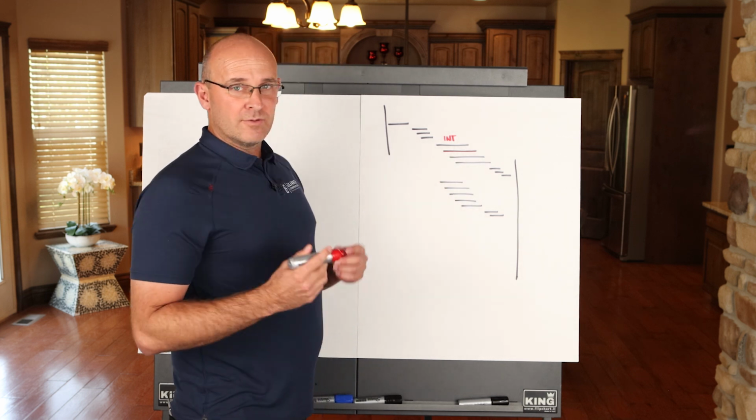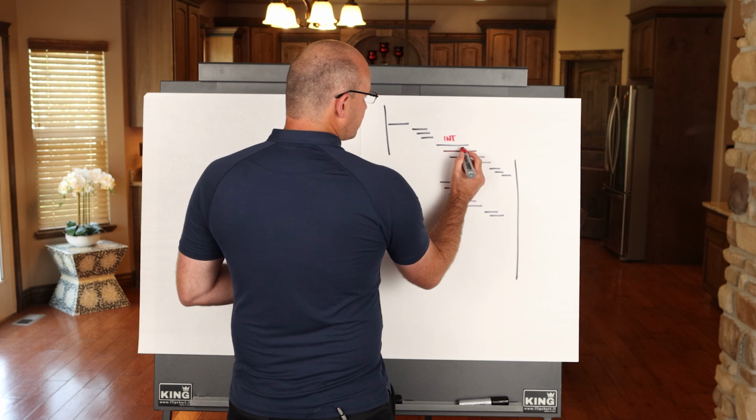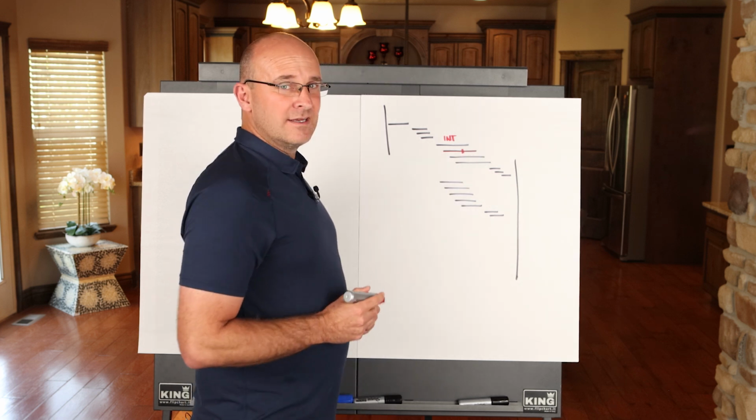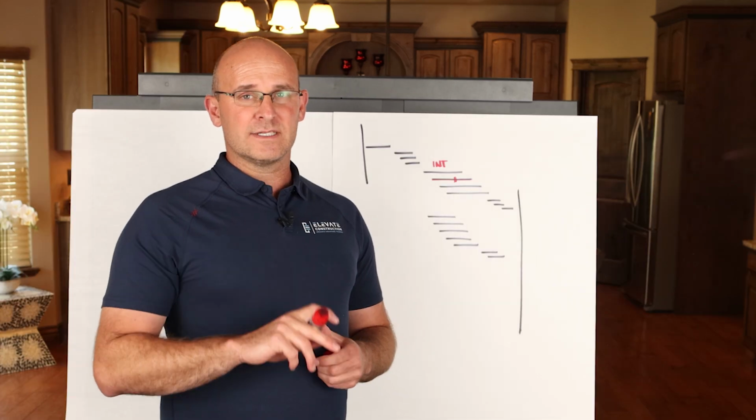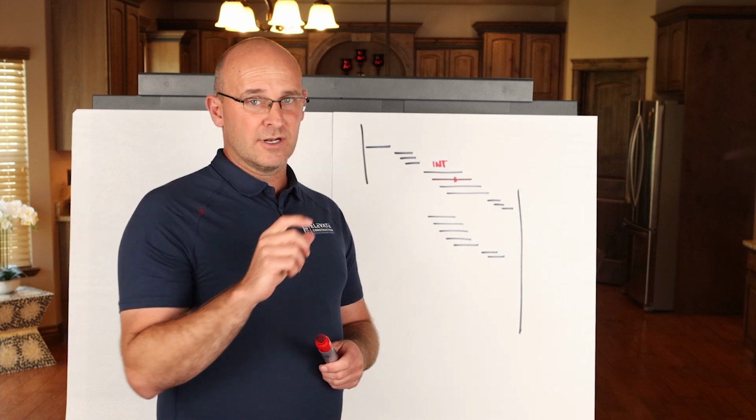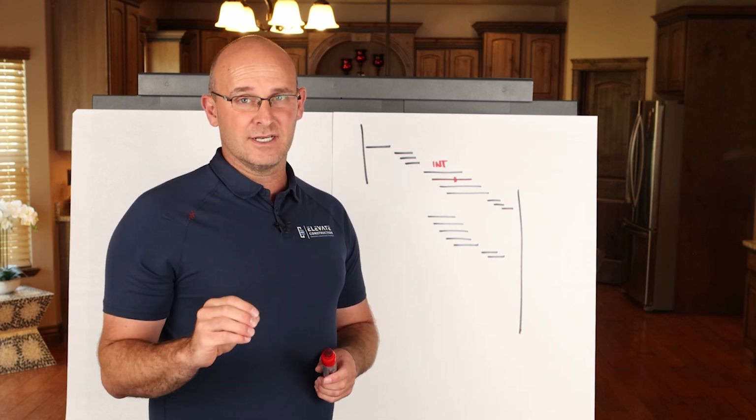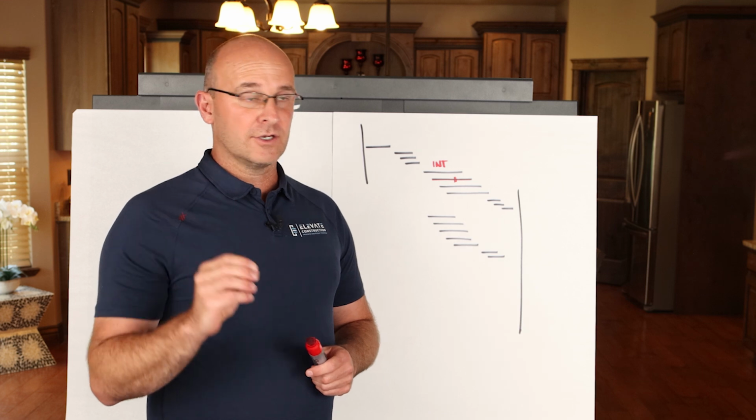There's a certain point right after paint where we need to start connecting the dry side and wet side. That means your duct and your hydronic piping to any HVAC equipment and your power and your controls.